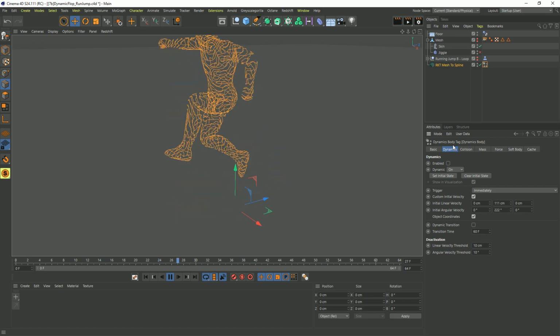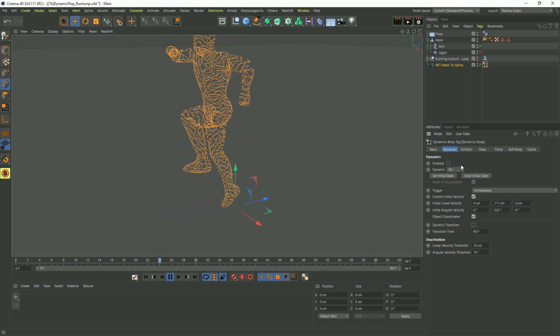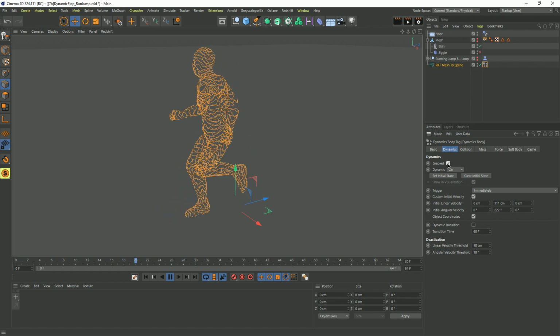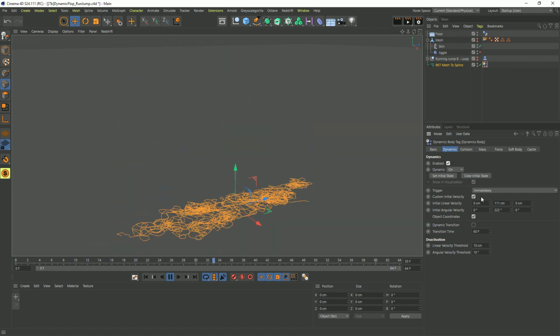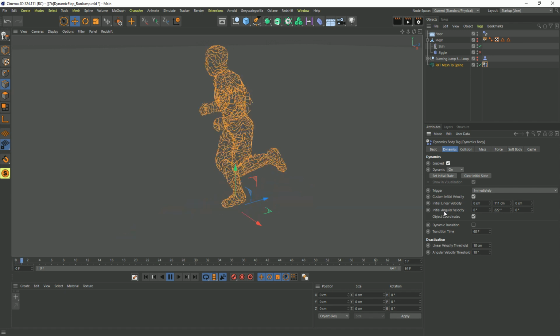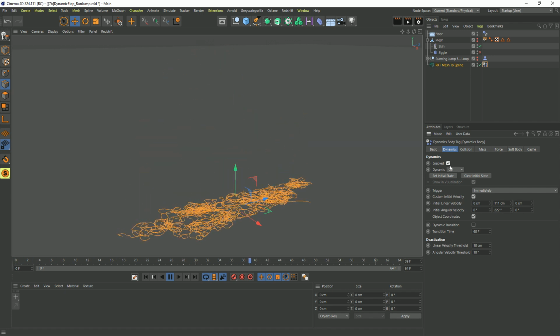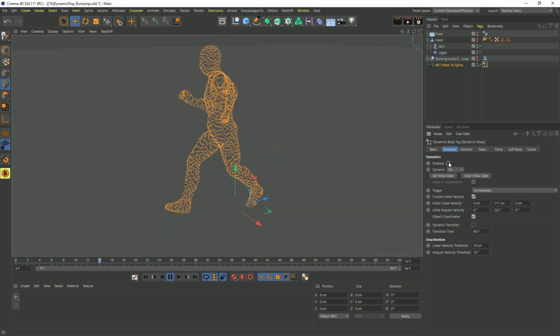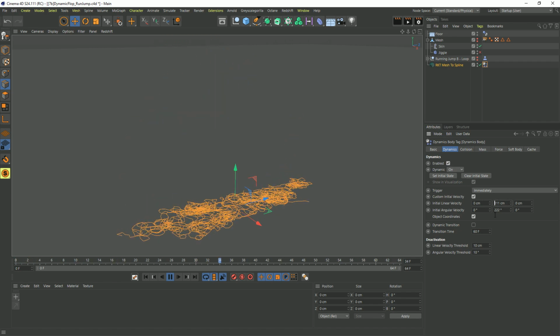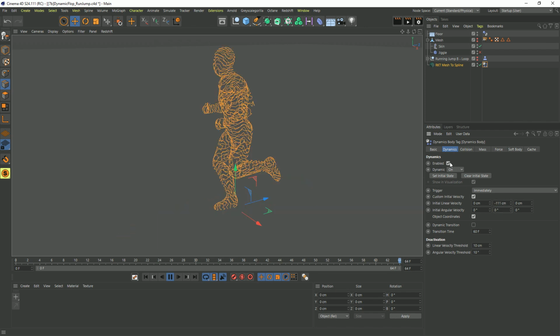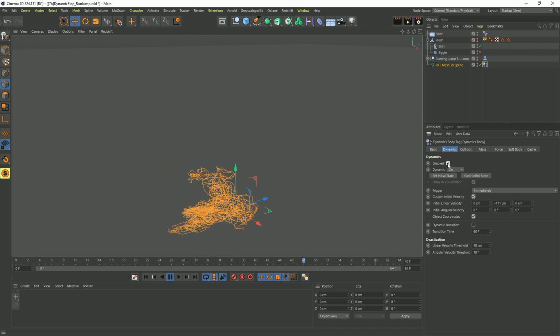Under the dynamics tab, I have disabled it. So as he's running, right when he jumps, I'm going to turn that on and you'll see it just fall over and flop onto the ground. It's got a little bit of initial velocity, a little initial angular velocity, so as soon as that turns on, that is activating. Turning that off, the character will just flop at that moment. Let's set that to go negative and just turn off the rotation. And then splat, falls into the ground. A lot of fun to be had here.